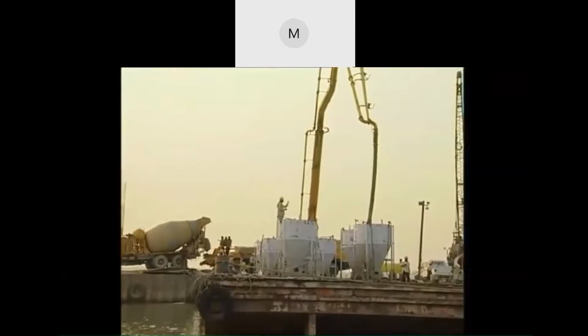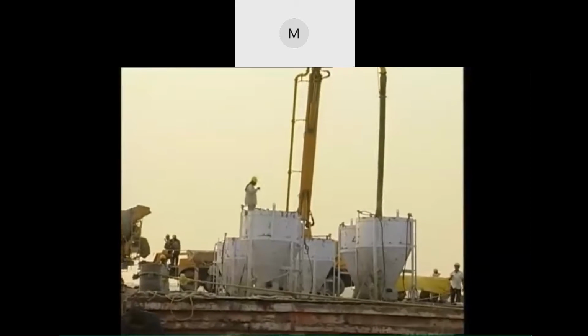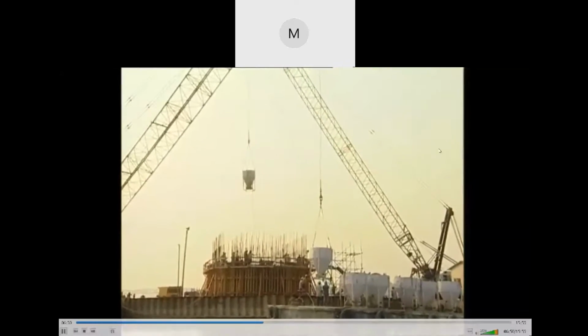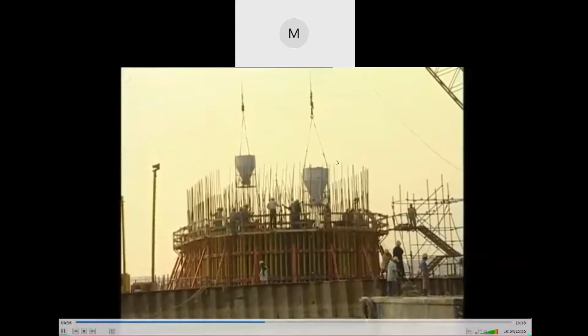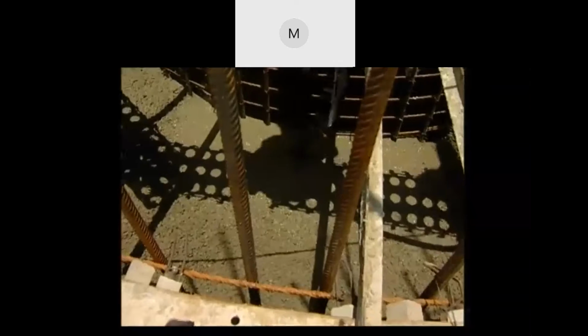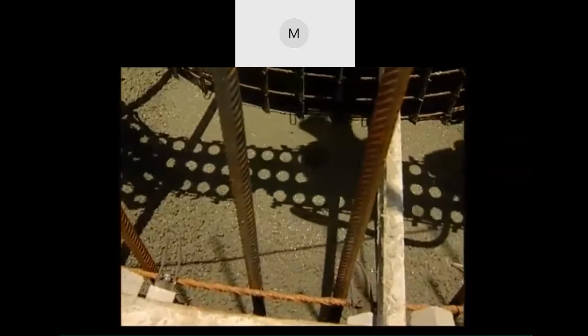The concrete is transported from the batch plant and is poured using concrete pump. For P17 well, the concrete is placed by crane and bucket arrangement. Concreting is done in clockwise direction in layers. The green concrete is vibrated using needle vibrators.